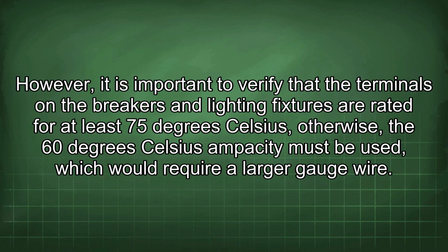However, it is important to verify that the terminals, the breakers and the lighting fixtures are rated for at least 75 degrees Celsius. Otherwise, the 60 degrees Celsius ampacity must be used, which would require a larger gauge wire.